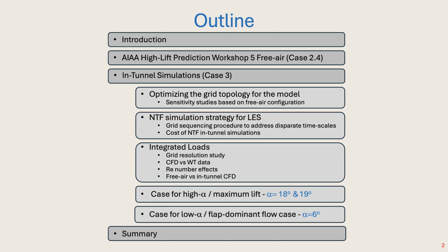So later we actually ran some internal simulations, and I'm going to focus mostly on how we can improve the grid topology. If someone really wants to have internal simulations with wall-model LES, that's almost impossible without certain strategies. So I'm going to talk about that, and I'm going to compare the integrated loads with CFD versus wind tunnel data, and some grid resolution studies.